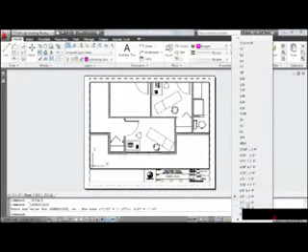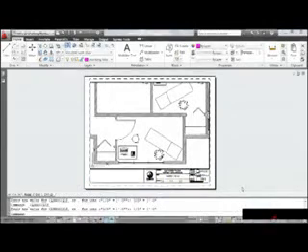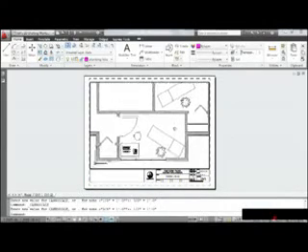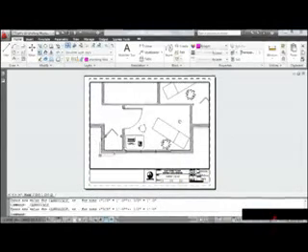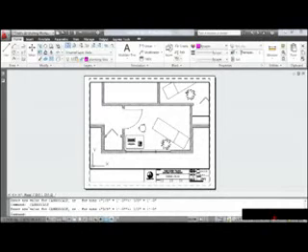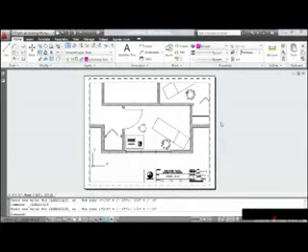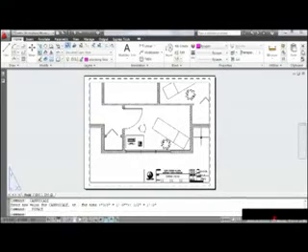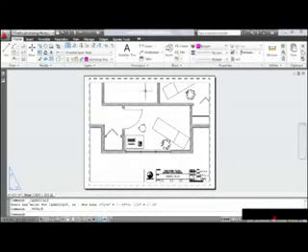I'm going to try 1/2 inch equals a foot. That looks like it'll work well. I'm going to recenter this, and then I'll immediately come back down and lock the viewport. Now that I'm finished, I'm going to jump out of the viewport by double-clicking outside the boundary. As I look at this, take a look at some of this extraneous geometry that we're seeing outside the room.